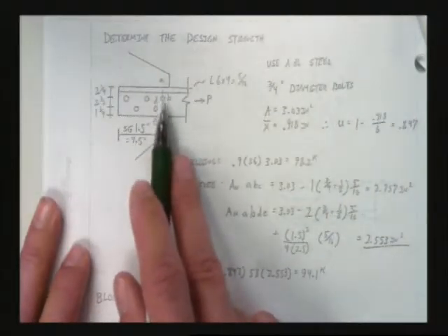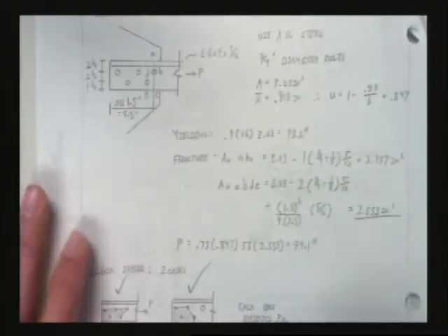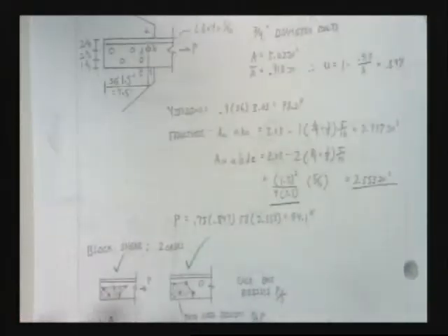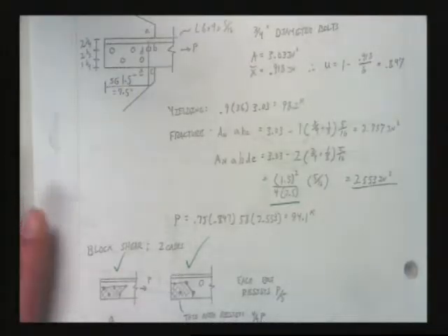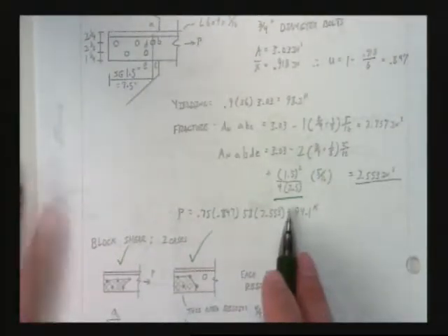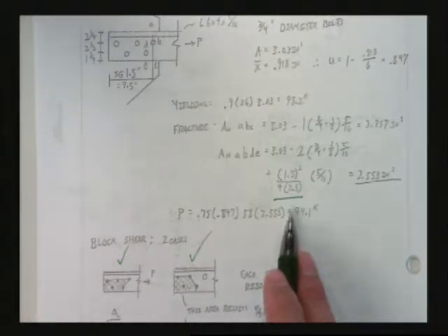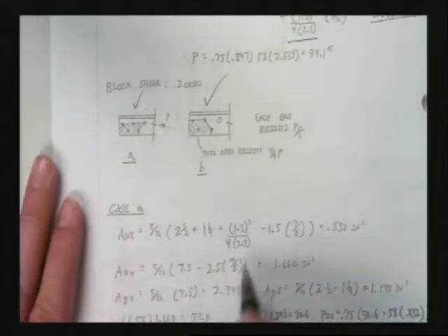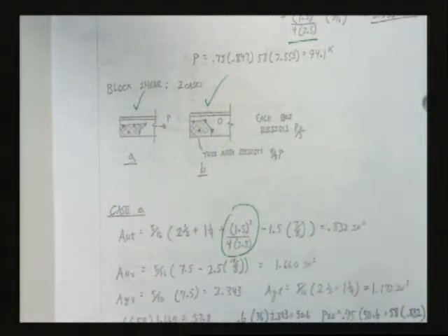However, right up here, when we did our fracture calculations, going from A, B, D, E, we use an S squared over 4G, and that is in the code, right? And that was finding a net area of tension, right? Yeah? Helped with that. Okay? So why don't we do the same thing? Why don't we use the same procedure? Why don't we use an S squared over 4G type term when we calculate ANT? And that's what we did right here.